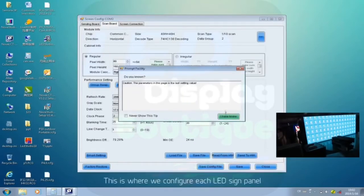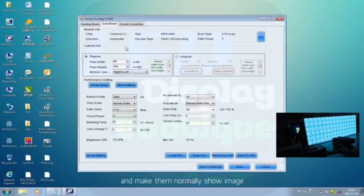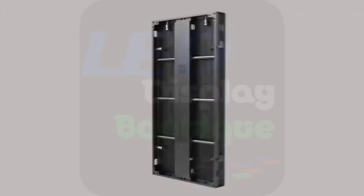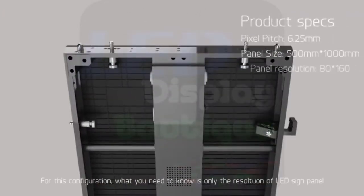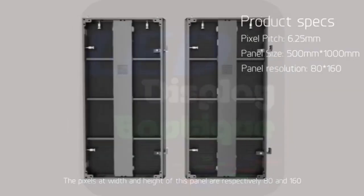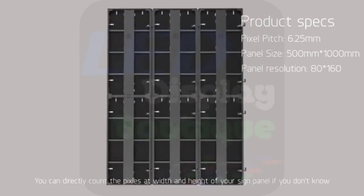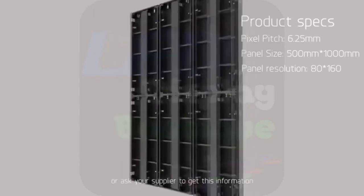This is where we configure each LED sign panel and make it show the image normally. Before we do any configuration here, let's go check the specification of this LED sign panel. For this configuration, what you need to know is only the resolution of the LED sign panel. The pixels at width and height of this panel are respectively 80 and 160. You can directly count the pixels at width and height of your sign panel if you don't know, or ask your supplier to get this information.